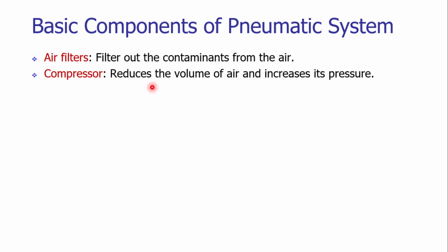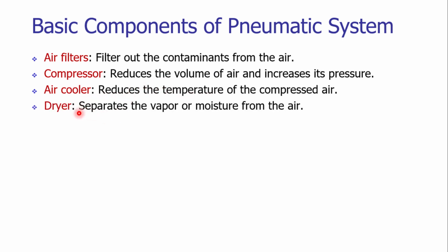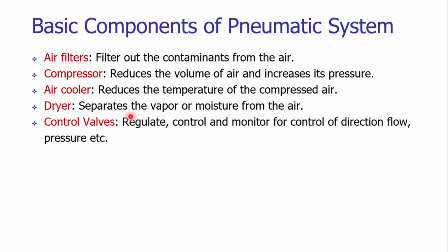The compressors are reducing the volume of the air and they are increasing the pressure of the air. The coolers are reducing the temperature of the compressed air. The dryers are separating the vapor or the moisture from the air. There are various control valves, and the control valves are carrying out their regular duties such as regulation, flow control, and monitoring of the pressure